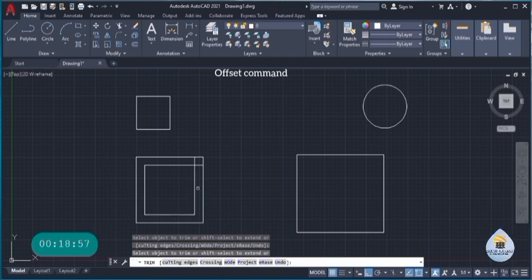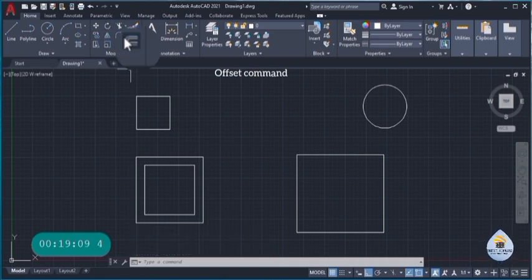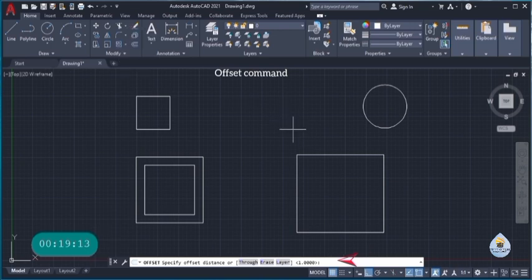You can see that, to the nearest boundary. So enter to get rid of it. Now that is for a normal line. Now for a polyline, if I click on the offset this way, it's saying specify first offset distance.